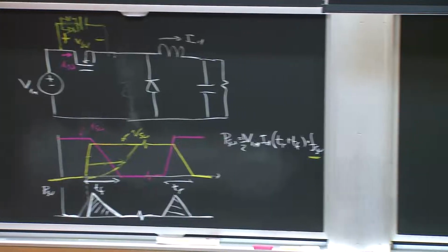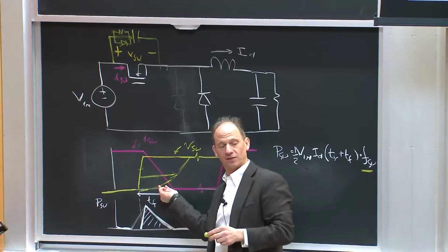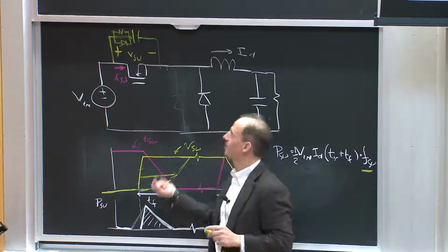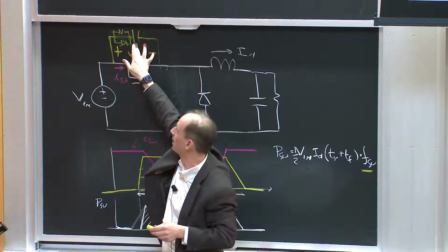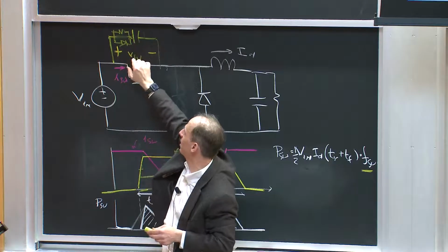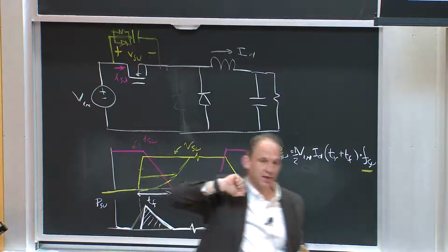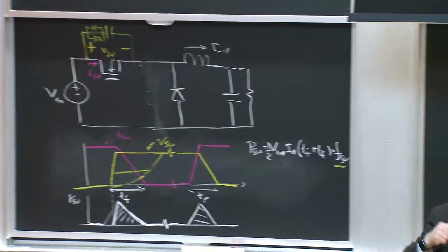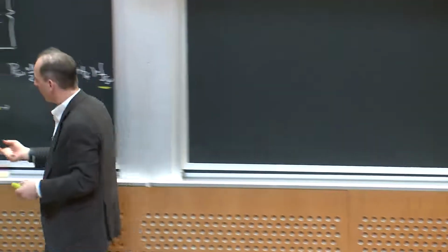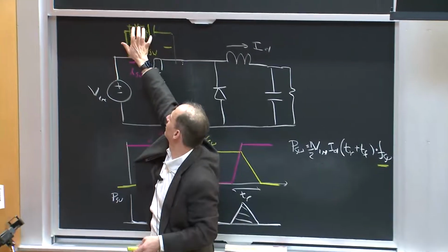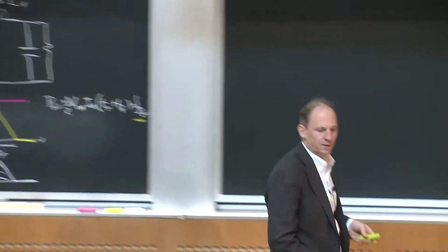And that works, and it does reduce the loss at turnoff. That's very nice. The penalty I pay is I put a bunch of energy in this capacitor, okay? And when I go to turn the switch back on, that energy ultimately gets dumped into this resistor, and in practice, typically I make the efficiency of the converter worse, not better, right? I've reduced the loss in the device, but I've more than offset that with loss in the resistor I get here. Okay?